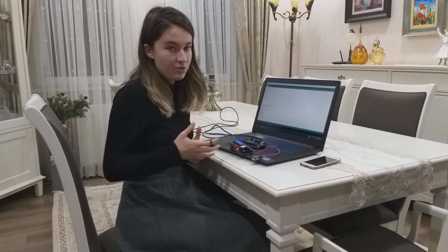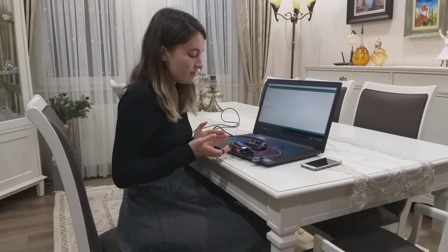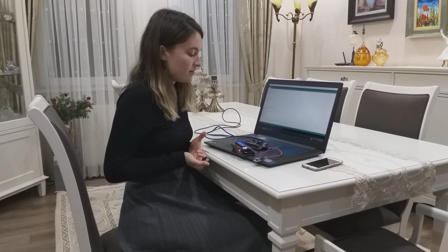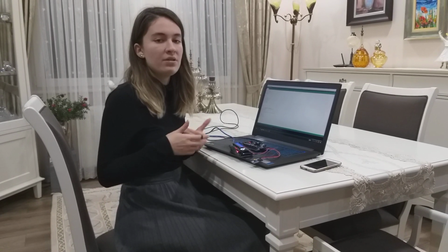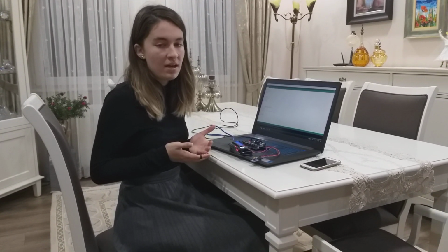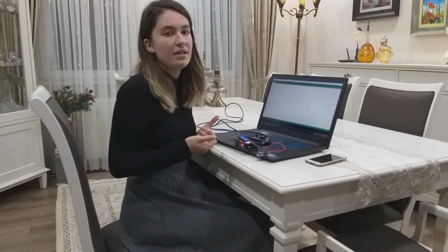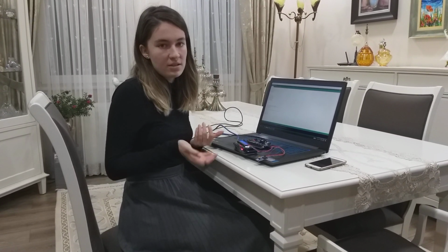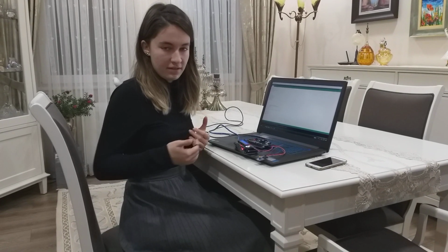I had to transfer this data into my Arduino, and I did this by once again writing an SPI protocol. This time in the SPI protocol, the Basys 3 was sending out the information and the Arduino was getting this information. Once again, it had enable inputs in order to start the communication between the two devices, as well as a reset one in order to reset the communication and stop it from recording.